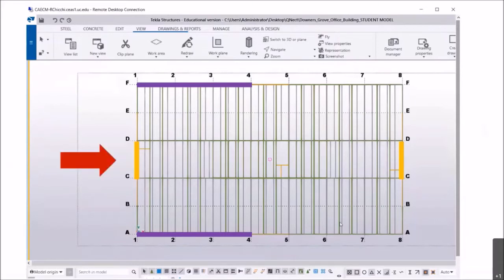So when we're applying a load in the east-west direction, we're going to engage the purple moment frames. When we're applying load in the north-south direction, that engages the yellow braced frames. And we also consider a combination of loading in both directions to represent more of an inclined load that's not exactly orthogonal to the building.